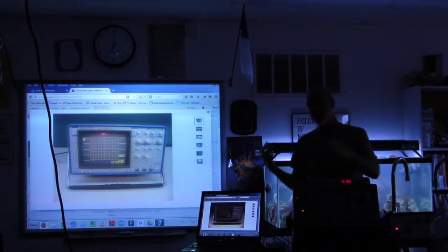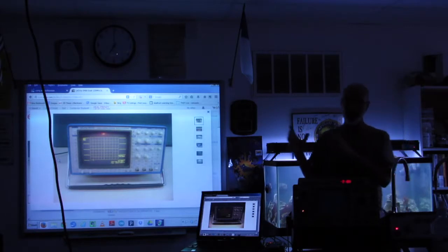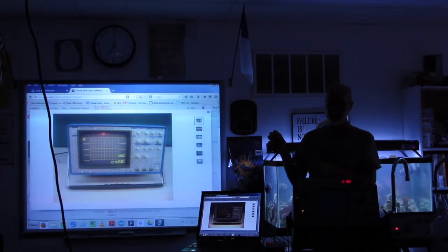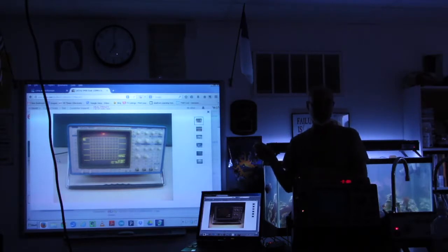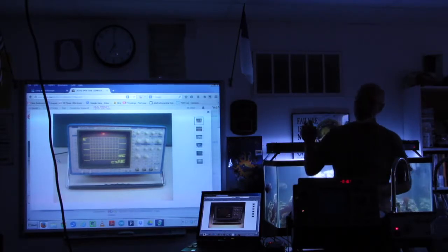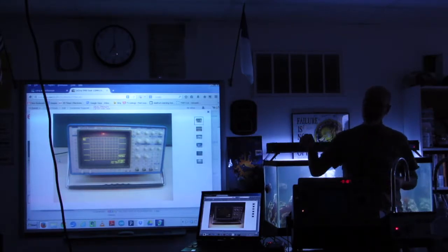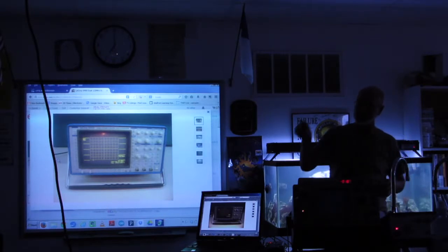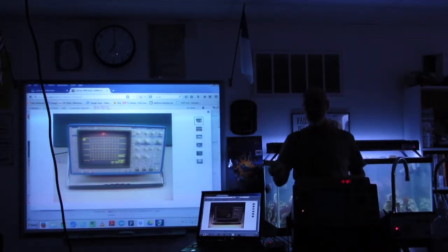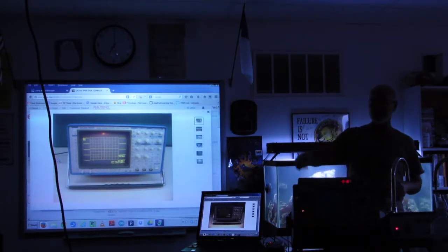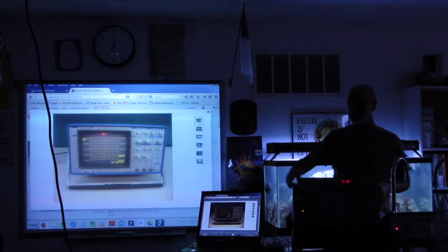Now, on the display end, most modern digital oscilloscopes have slow LCD displays, and there's no way in the world you can display a real-time high-frequency signal on an LCD display. So instead, on the display side of the digital oscilloscope, you've got a slower circuit that reads the data out of the RAM much more slowly, a speed that's appropriate for the LCD display.